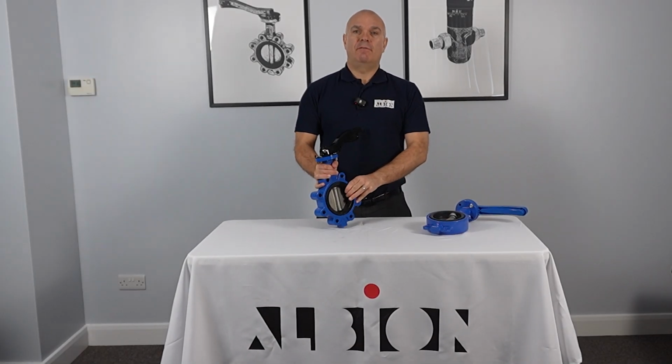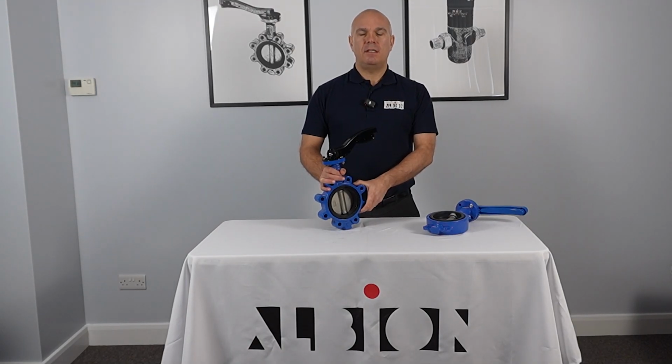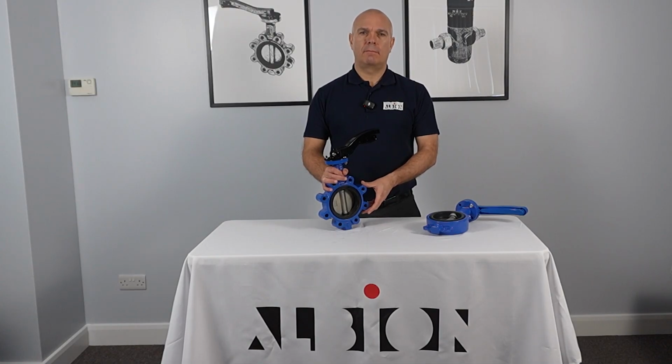A valve seat in a butterfly valve provides a sealing surface between the disc and the valve body, ensuring a tight shut-off when the valve is closed. It prevents leakage of the fluid by creating a seal against the edge of the disc. The seat is a critical component as its material, design and condition directly determine the valve's sealing performance, durability and suitability for different applications. Albion's range of butterfly valves come with either EPDM or NBR seats. It is important, however, that due consideration is always given to on-site medias and service conditions when determining which type of butterfly valve to select.